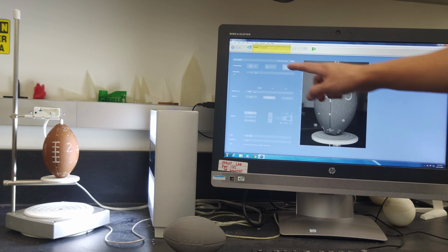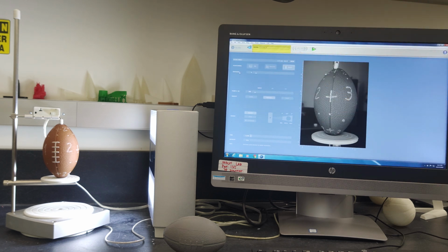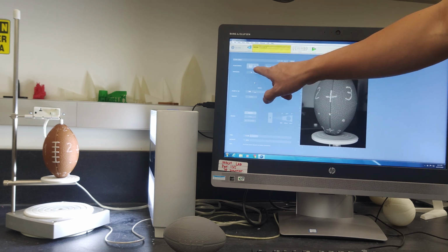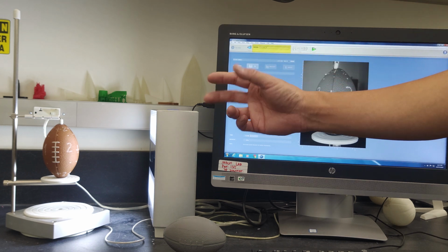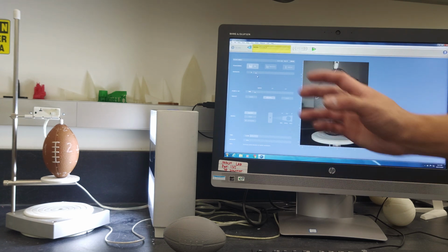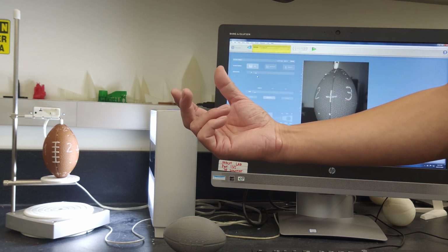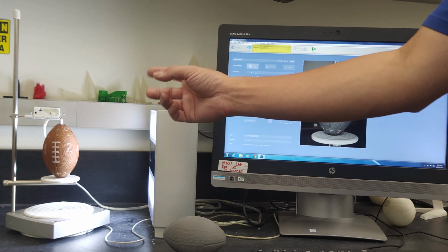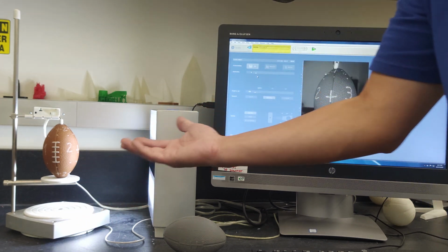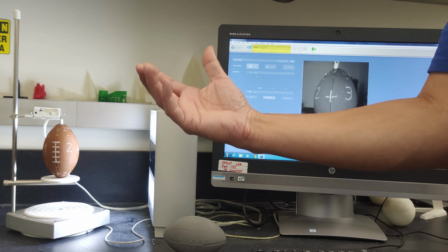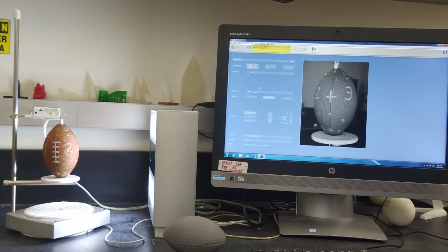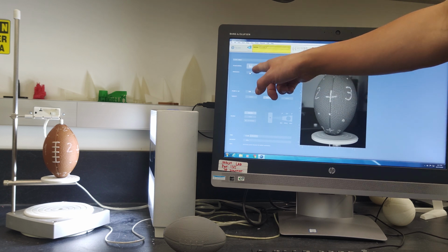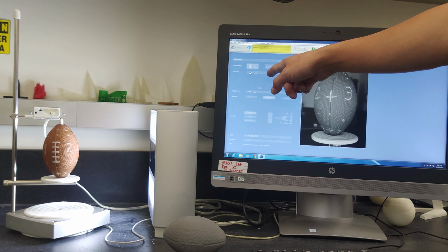Below the positioning option is the divisions option. That defines how many angles the turntable spins each time. The minimum is 4 and the maximum is 16, which means if you set the divisions to 4, each time the turntable will turn a quarter of 360 degrees, that is 90 degrees. Then if you set it to 16, each time the turntable will turn 22.5 degrees.